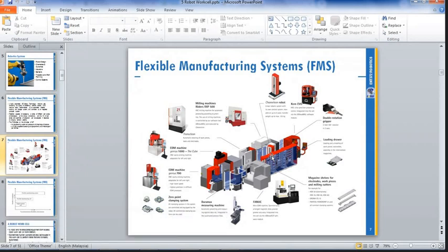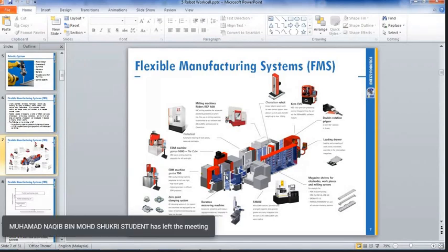They do that because they don't want to move the wafer on the floor, because if we move on the floor, we have a lot of vibration and a lot of stoppages. When we have a lot of stoppages, the wafer is a silicon material, so the wafer will shake. If the wafer shakes a lot, particles will occur. Particles, because silicon is like glass, it's brittle, so it can produce dust, something like dust. That causes rejects of the product in wafer fabrication. So they carry the wafer using a robot located on the shielding side, the top side.